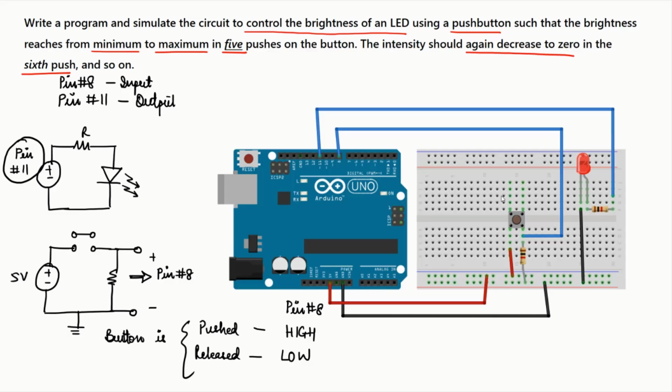The important aspect that I was talking about when we talk about a mechanical switch like a push button is the concept of debounce. Many a time what happens, and this is not an error, it is just a physical constraint of any physical or mechanical device, is that the moment you press the switch, ideally both these brushes should make contact immediately.